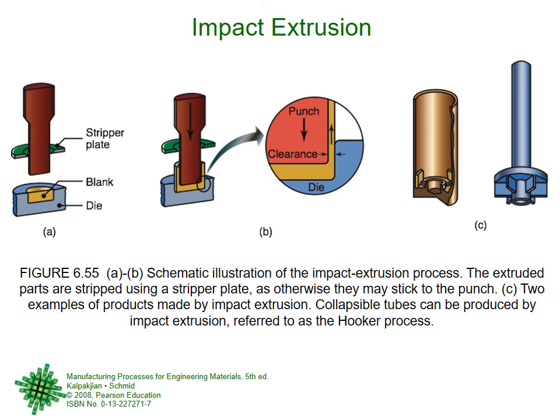But indirect extrusion is not continuous. In direct extrusion, after extrusion, a long continuous length is coming. Here, one can at a time, because it will go back in the same direction. You have the press from here, sudden impact load, it will go back in the same direction. So a can will be formed, but it can't go to a very long length. So one can length, and then you pull it back, put the second piece, boom, second can, third can, fourth can, right?